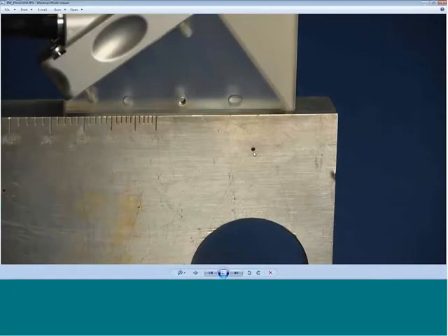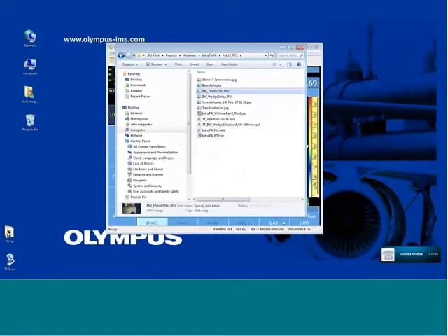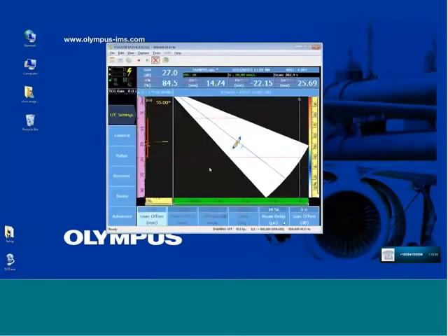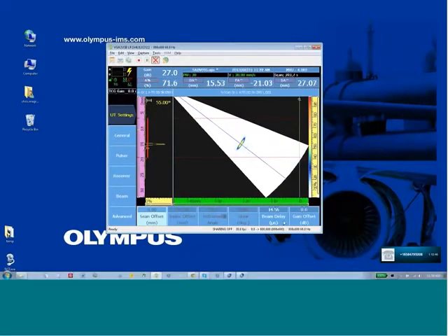So my focus, my frequency, the probe aperture is all relative to the quality of the signal. Again, here is a 16-element aperture. I can see that it's being detected by multiple A-scans because of the beam spread.